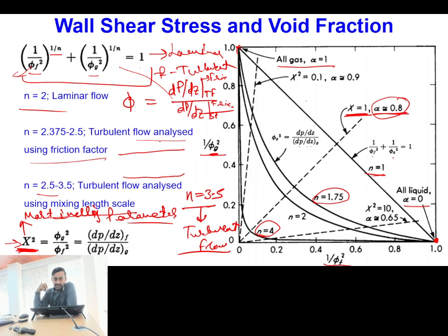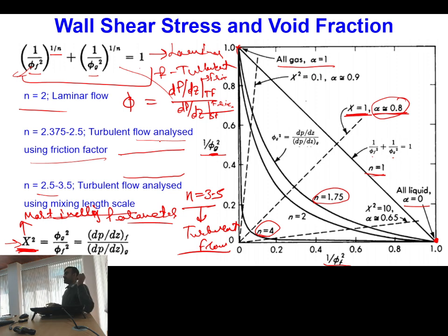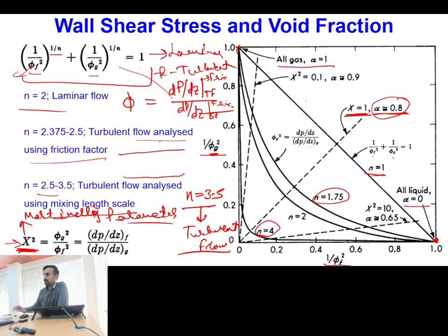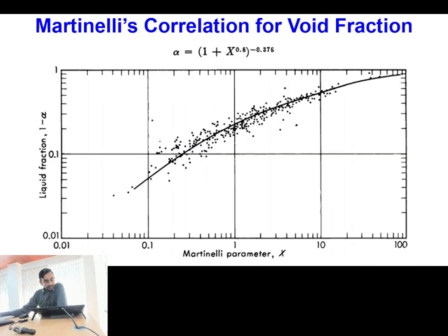Under these conditions, thousands of experiments were done using different conditions, and then people came up with some empirical equations and empirical plots, based on which one can simply use the values of phi f, phi g parameters and then calculate the value of pressure drop for practical conditions.